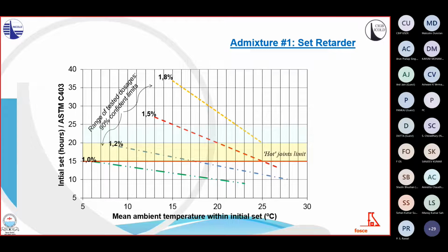The primary objective is to delay the setting time of the mix in order to be able to place the next layer within the initial set of the surface of the receiving layer beneath.